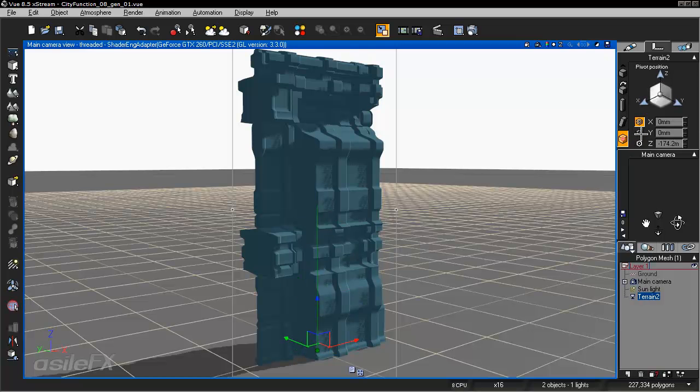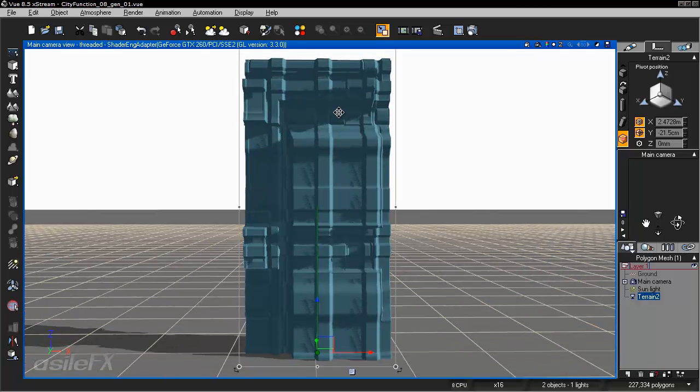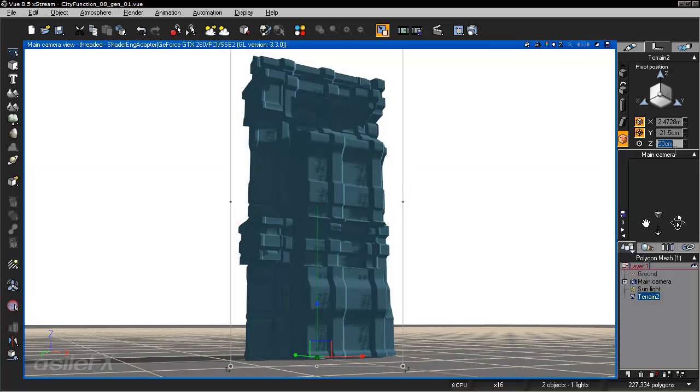So it's either showing as a subtraction from the object center or the current state, or the actual location in which the pivot is in the scene. We'll go ahead and set it to 0. Making sure that the pivot on the bottom is important because it is typically used to place your objects onto the surface on which you're creating an ecosystem. If you need to give yourself a little bit of leeway, we could bump that up a little bit. I'm going to go ahead and set it to 1.